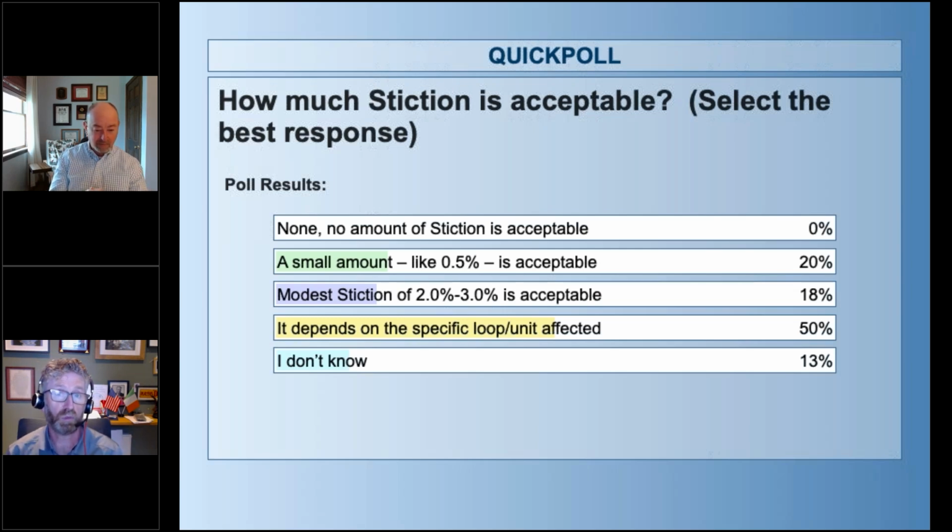It's not going to cause a problem, George, but I suppose you're being proactive about your process. At 1% stiction, you've lost 1% control of your process. So on a 0 to 100 instrument, you've technically lost about 1 degree of control. Now, if your process needs to be tighter than that, that's the measurement of it. Percentage stiction is the loss of control, I suppose. So it's that proactive measurement.